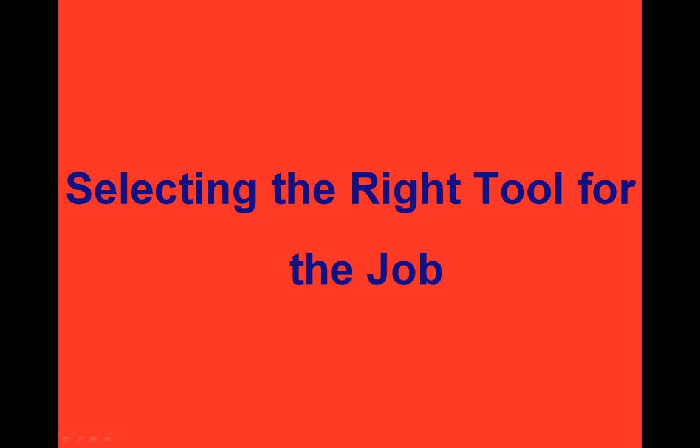So the major three takeaways that I would really like to emphasize here: first, selecting the right tool for the job. Hopefully we explained that the importance is your downstream application. What is your purpose for measuring or scanning a part? What is your intent to do with the data after you scan it? That determines the best tool for the job: what is the best digitizer, size-wise and accuracy-wise, what software you want to use, and then bring the data into CATIA.